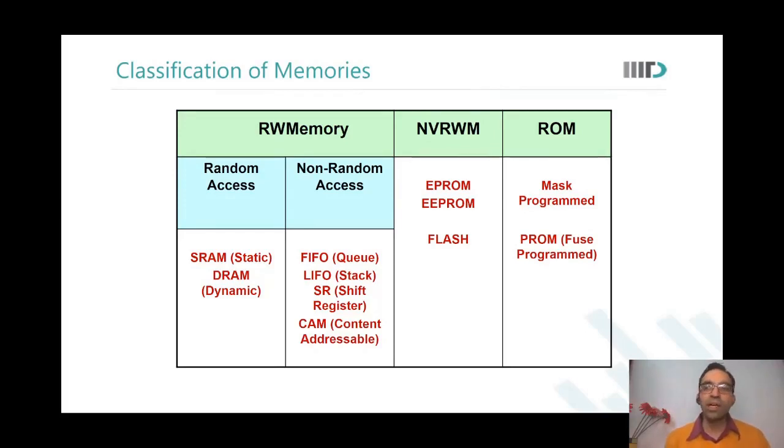Okay. And do you realize that if I have to do this kind of operation, it will be very high speed, obviously. Instead of 100 cycles, I could do that compare in one cycle only. But there is a much bigger area penalty because now there is a comparator in every cell.